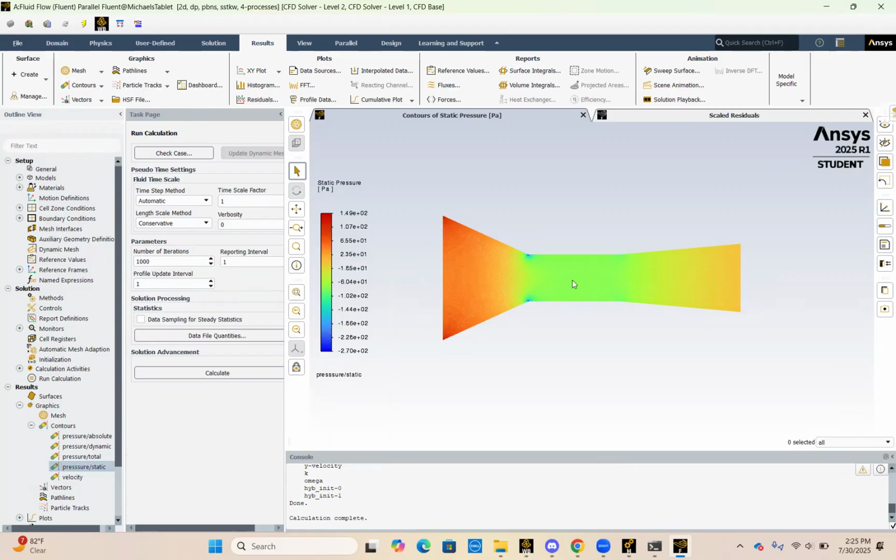As the contraction zone moves or squeezes the airflow into a tighter space, assuming that mass flow rate has to stay the same, then velocity has to increase, and then because of that we see an increase in velocity, but as you can see, a decrease in pressure, and then as our diffuser expands it, right, the pressure is going to rise again.